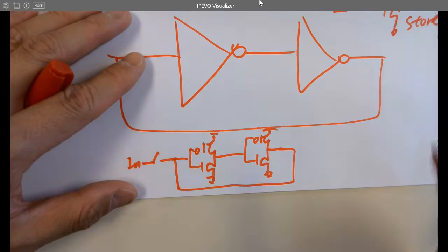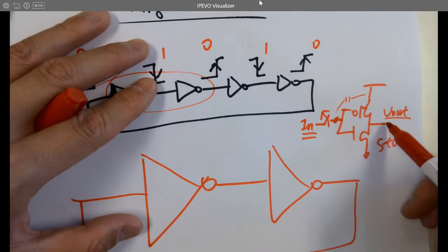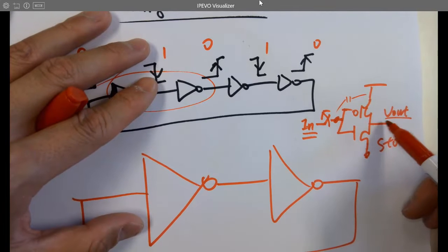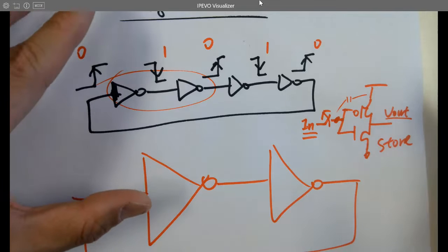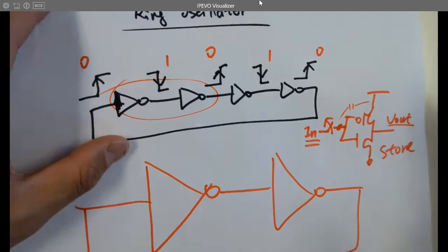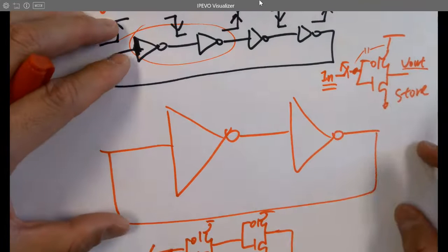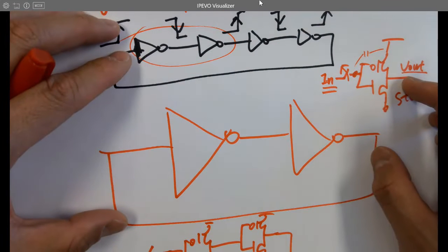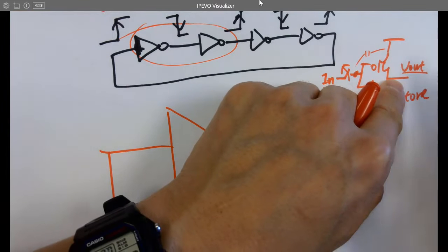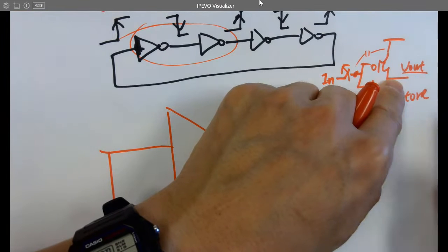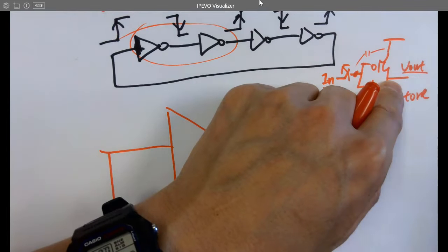So my question for you here is, if you have one inverter and you open a switch, the answer is you're not getting anything, right? If you probe it, it can be 0, but you don't want to say 0 because it's not ground, just a floating wire without anything, right? Yes, if you probe it, it's going to be 0, but it's not a strong 0, right? 0 and nothing is different because 0 volt is considered as ground. It is able to discharge a lot of things. But it's a floating wire, so it's not 0.